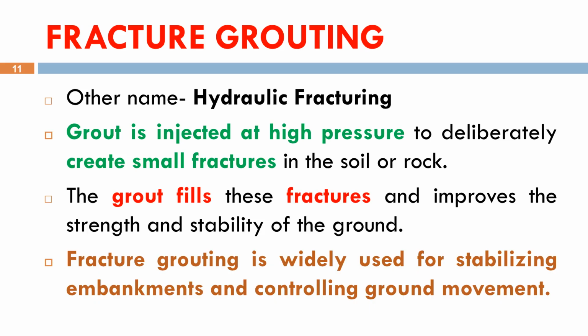Unlike permeation grouting, which fills existing pores, fracture grouting creates new pathways for the grout. This technique is commonly used to stabilize embankments, rock foundations, and dam structures, especially where the soil has low permeability and ordinary grout cannot penetrate effectively.